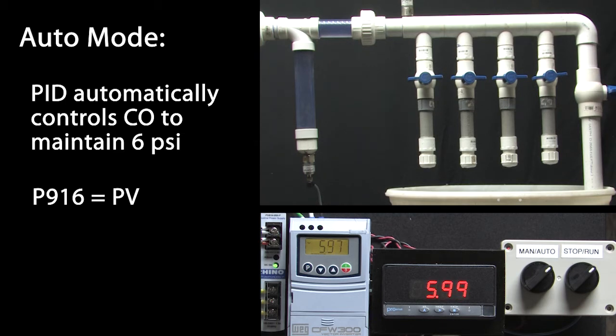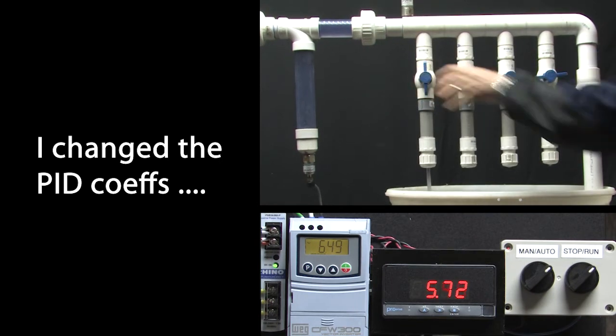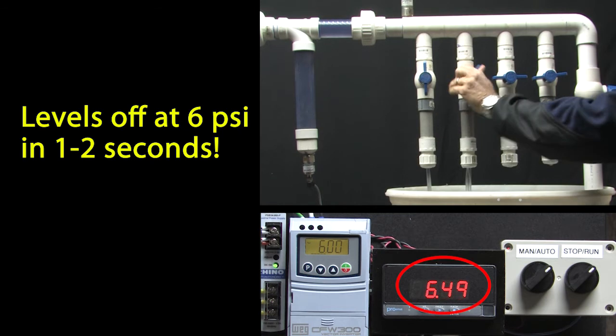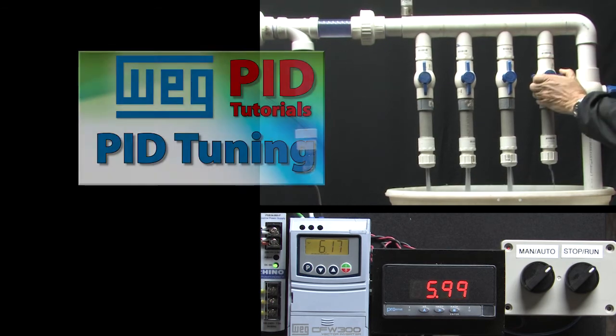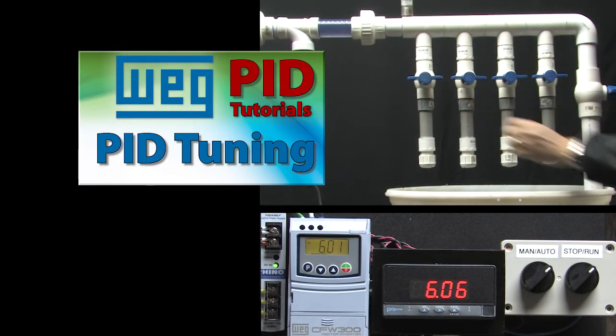Very cool. But there's a problem. It's taking around 10 to 15 seconds for the system to settle out. Can we make it respond faster? Yeah, we can. For example, with the PID parameters optimized, now when I open and close the valves, look how fast the system responds. It settles out at 6 psi within a second or two, even for the no valves open case. And it only took me a minute to optimize the PID coefficients. So if you want to learn how to do that, be sure to check out the PID tuning video where we'll do that, and we'll run some examples to help you get a better feel for how PID works.